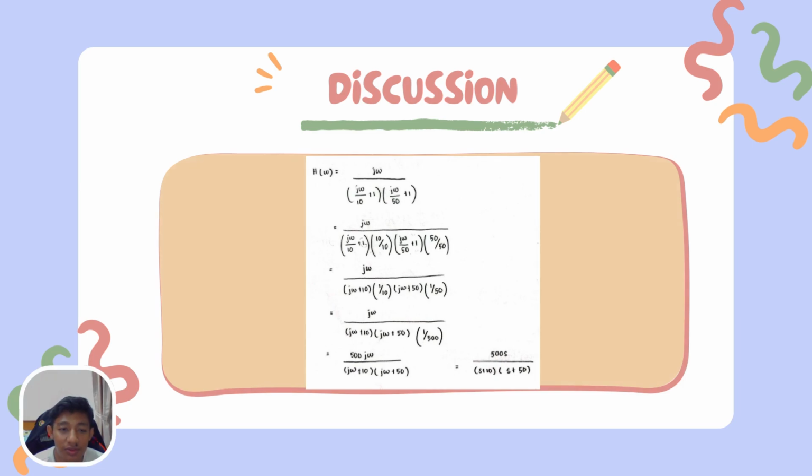So in this discussion, we learn how to draw the Bode plot and how to calculate the transfer function from the Bode plot. In this slide I have shown you the calculation, which is H of omega equals j omega over (j omega over 10 plus 1), and then (j omega over 50 plus 1), and then we just need to calculate it. We need to eliminate the 50 to make the equation a general equation, which is j omega over (j omega plus 10) and (j omega plus 50). So how do we eliminate it?